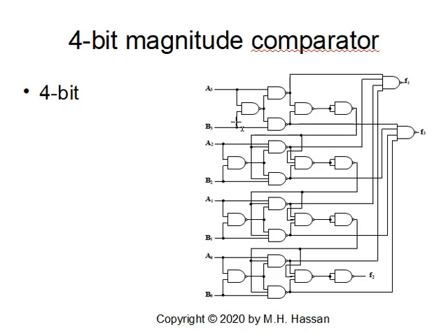Also, we take the 4 outputs from here to get F1. For the number A to be greater than B, we need the function F1 to be 1. So we take the output from this NAND gate, this NAND gate, this NAND gate and this NAND gate. All of them go to the 4-input NAND gate to get F1.